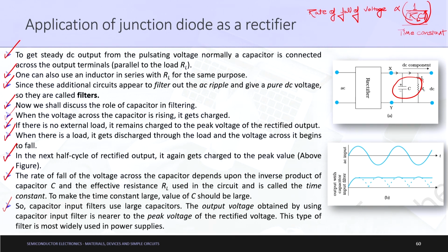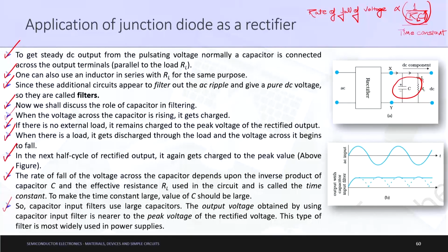So, what are all the concepts we understood in this? First of all, we started with the discussion of the half wave rectifier, in which we understood that, let us say there is an AC voltage. For each half sinusoid which is forward biased, we get the same output, but when it is reverse biased, the current is 0. So, only the half wave is rectified.